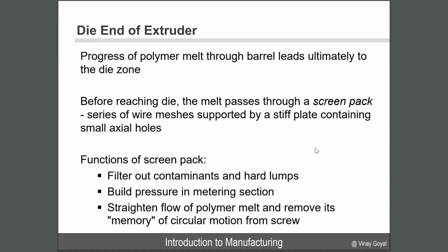And what is a function of that? It filters out contaminants. That's one of the things it does. And any hard lumping that occurs, it breaks those apart, which is why I called it the breaker plate. Also, it builds pressure in the metering section, which is very nice because now when I'm pushing through that tube,